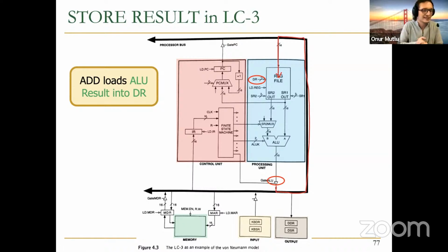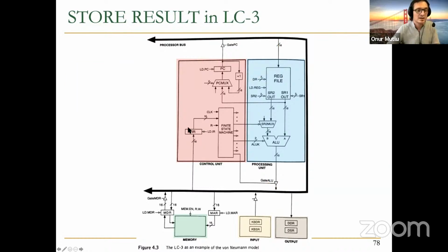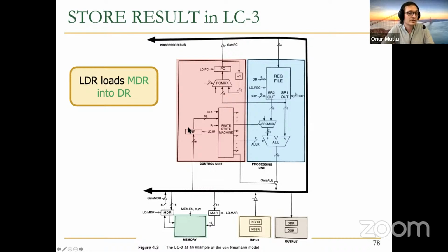Makes sense, hopefully, right? So basically processing happens in multiple clock cycles, and you orchestrate the control signals so that the right thing happens at the right clock cycle. And you can orchestrate the control signals because you know what instruction is being processed in the instruction register, right? Okay, so for LDR, load register, remember the data value was in the MDR. It gets placed into the destination register because LDR is a different instruction, right?